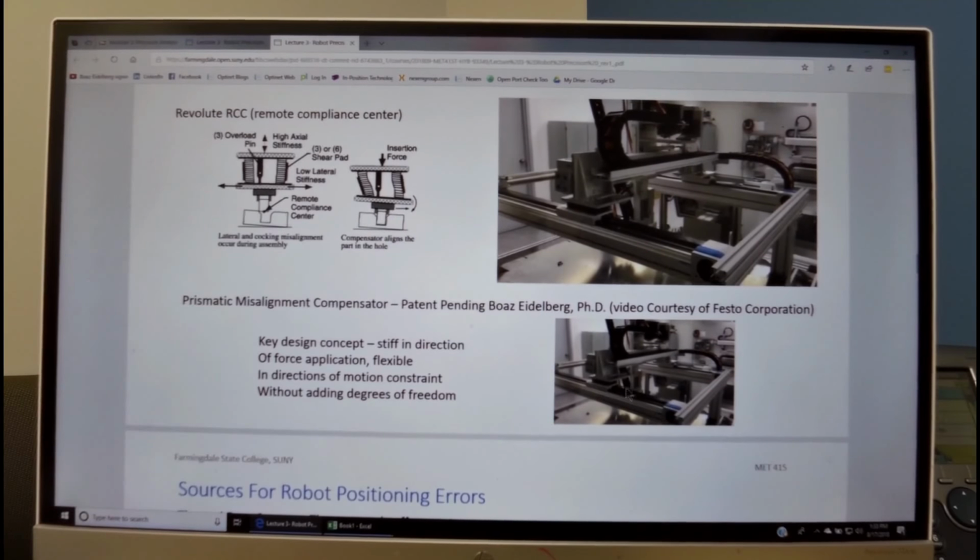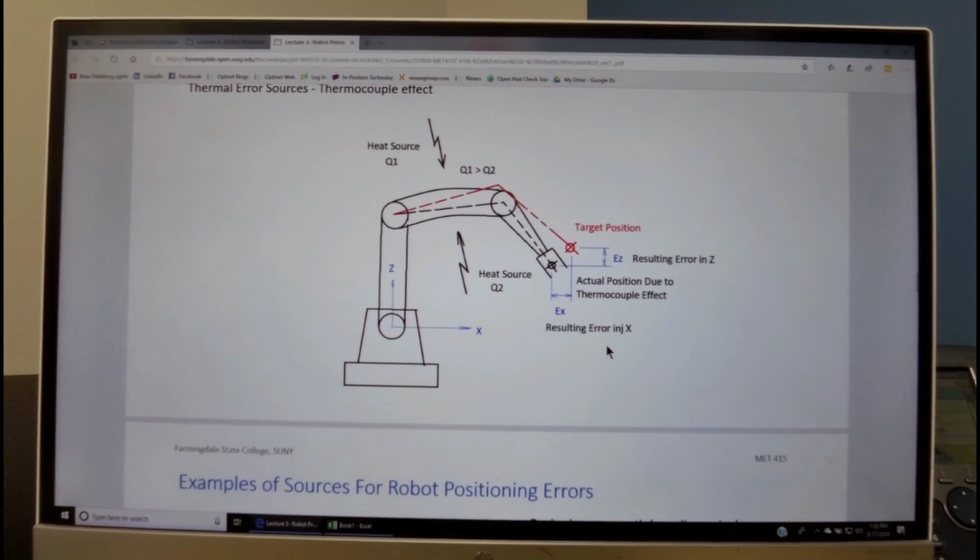This is a Cartesian robot, and you see the black element over here is a flexure done from composite material, printed composite material, one part that allows the crosslink to expand during thermal deflection, or if, for example, the two long axes are not parallel, and give while keeping the stiffness in the direction of motion very high. So these are mechanical ways of solving some of these errors.